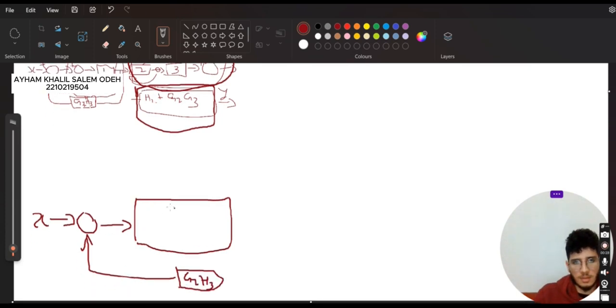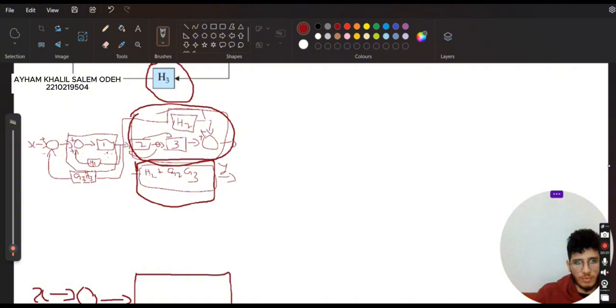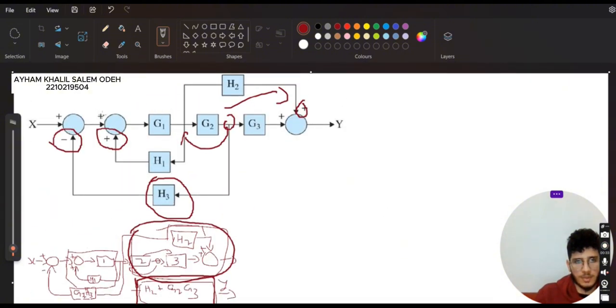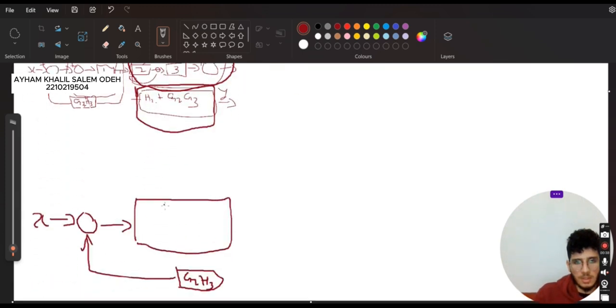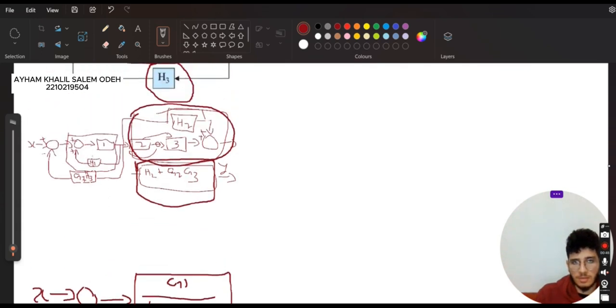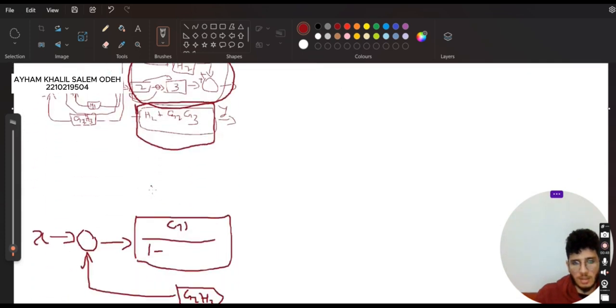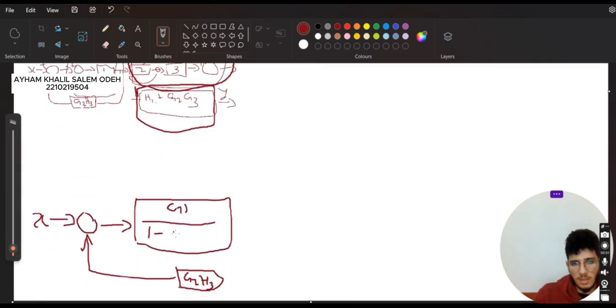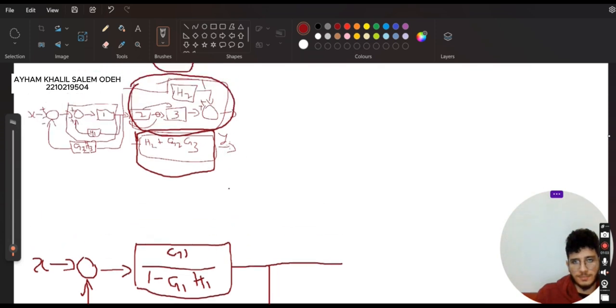As for feedback, this small feedback over here, it's going to be G1 over 1 minus, because it's a positive feedback, therefore it's going to be a minus over here, G1 H1, and here we go, over here and over here.